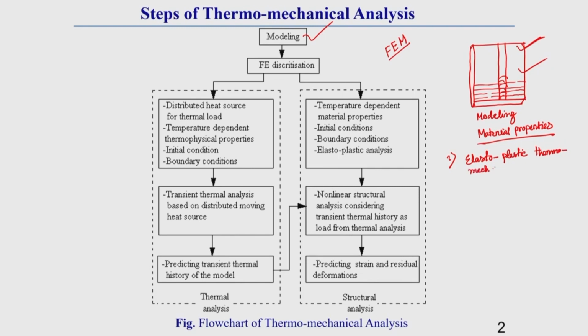By this elastoplastic thermomechanical analysis we can find out the residual stress distribution in the weldment. So it consists of a thermal analysis as well as a mechanical analysis.